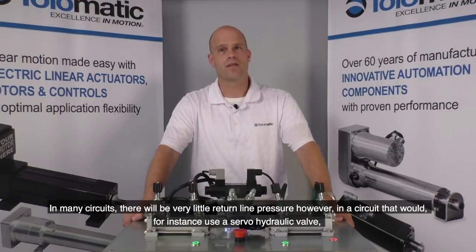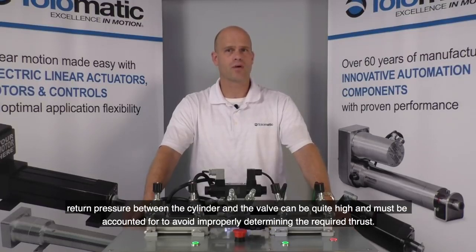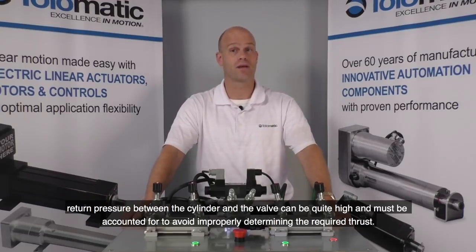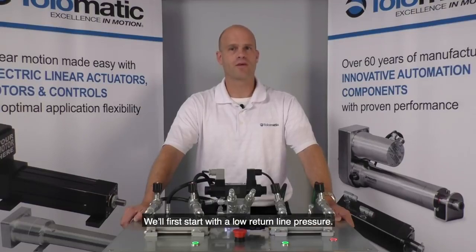In many circuits, there will be very little return line pressure. However, in a circuit that would, for instance, use a servo hydraulic valve, return pressures between the cylinder and that valve can be quite high and must be accounted for to avoid improperly determining the required thrust. In this video, we will demonstrate both scenarios, one with high and one with low return line pressure. We'll first start with a low return line pressure.